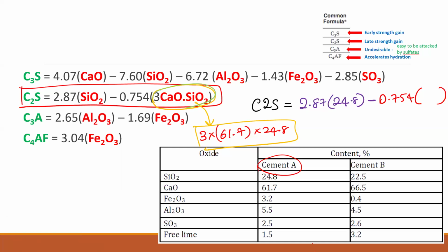If you go to the first few slides, isn't that one already C3S? Yes, that is the expanded formula of C3S. C3S is the abbreviation. C3S is 3 times calcium oxide times silicon dioxide. So that is the abbreviation, and this is wrong. You need to have 13.9 or 14, which you have got there. Does that make sense? Yeah.